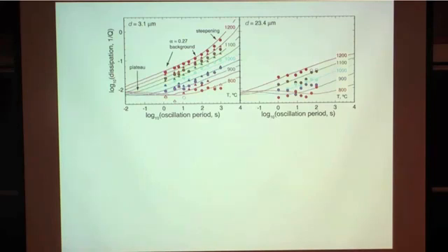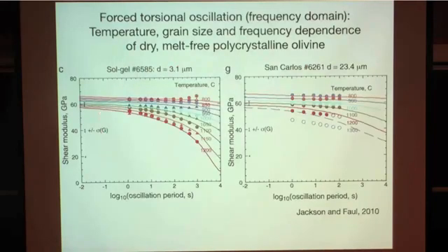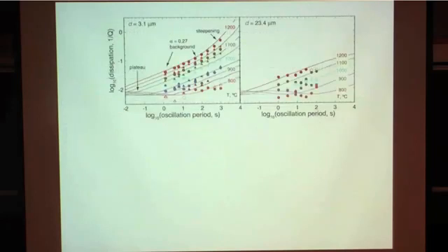Right? That's the same as what we saw here. We fix temperature, we vary the period, and the modulus decreases. This is the other side of the coin. The two go exactly together. The decrease in the modulus is directly related to the increase in dissipation. And that's this absorption band, right? This is this alpha that came up yesterday.